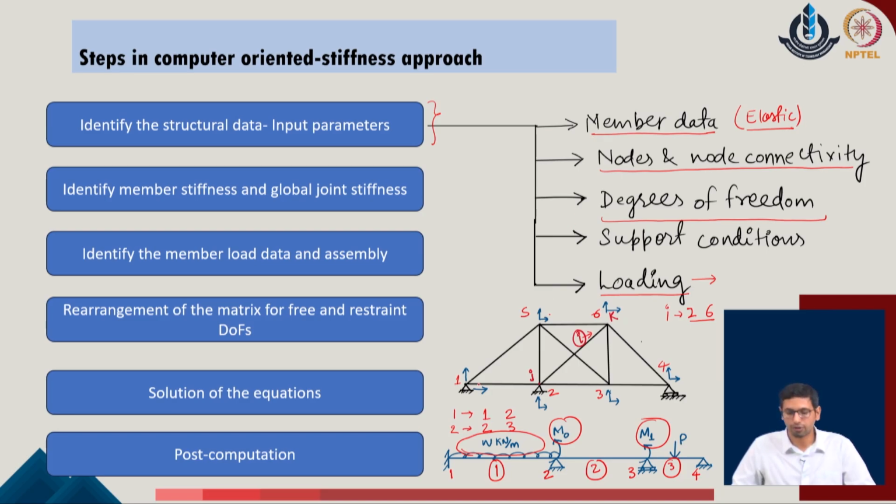So, if in a software tool I am able to draw a truss like this, then the software module is able to understand that there are different members which are labeled like this, and for each member the software is also able to understand what the connecting nodes are. In a similar manner, when the user selects a given material case and assigns it to a member, the software understands the member data in terms of its material properties and geometrical properties.